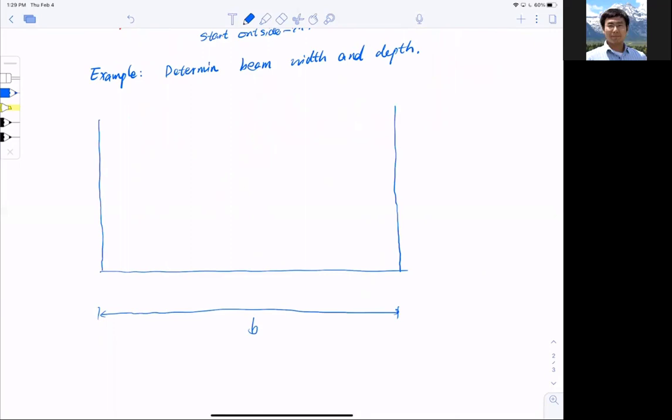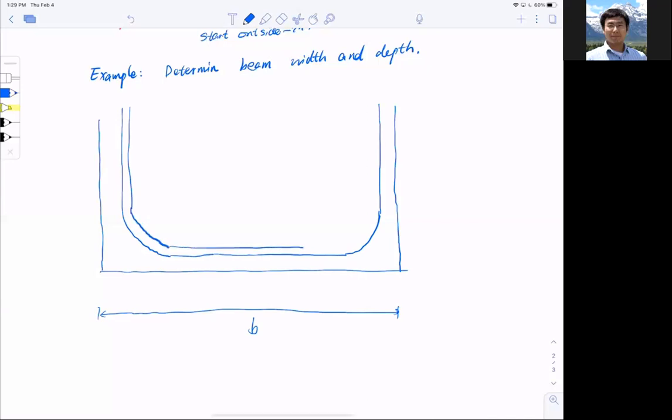And before that, I want to put the stirrups down. So the stirrups go here like this, and mind you that it has a curvature like that. Then it goes horizontal all the way, almost to the edge, and does another semicircle, and then straight. So if I'm using, say, number 3 stirrups, this is 3/8 of an inch in diameter, where I stop right here and do a curve and go straight again, stop here, do a semicircle curve.